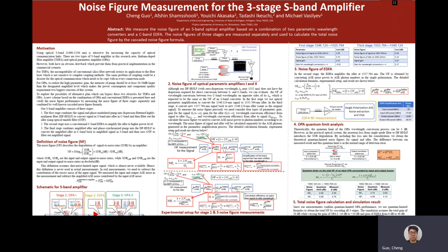To explore the possibility of an alternative plan, which can bypass these two obstacles for TDFA and OPA, a new scheme based on a combination of OPA and conventional EDFA is presented here, and we verify the noise figure performance by measuring the noise figure of the three stages separately and combining them by the well-known cascaded noise figure formula.